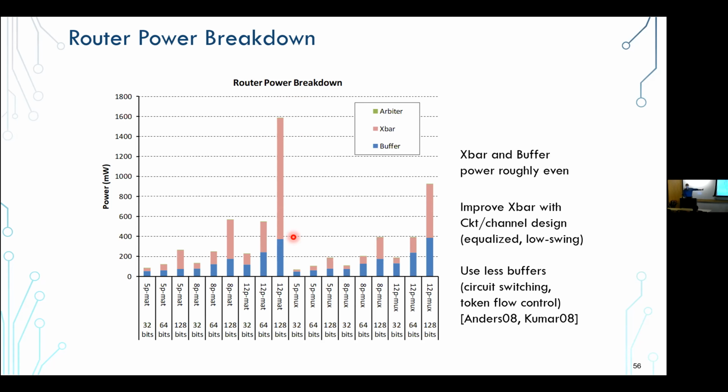We're here talking about 18. As you can imagine, for 256, the wiring complexity becomes much bigger. You have something on the order of a reticle-size switch, right? So you have to traverse centimeters' worth of wiring. And there are all sorts of techniques, low swing, whatever you can do to minimize this energy, that make the router power efficient.